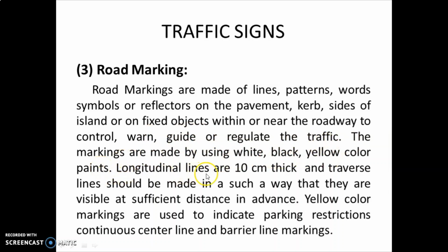Longitudinal lines are 10 cm thick, and transverse lines should be made in such a way that they are visible at sufficient distance in advance. Yellow color markings are used to indicate parking restriction, continuous center line and barrier line marking.